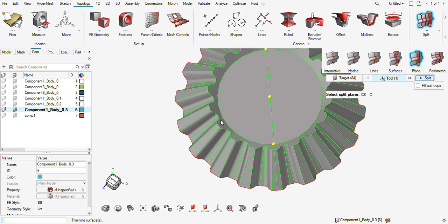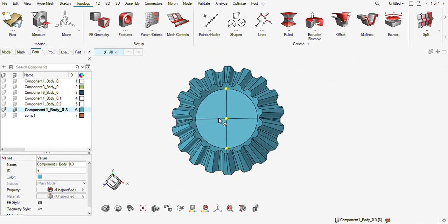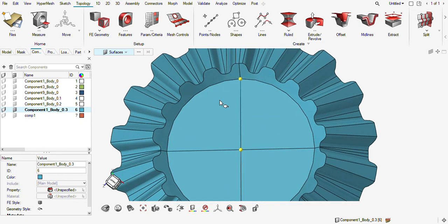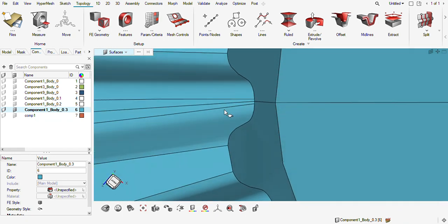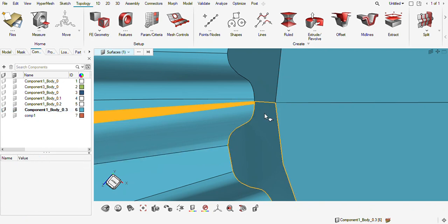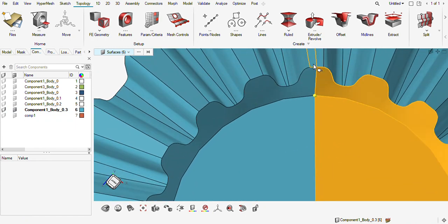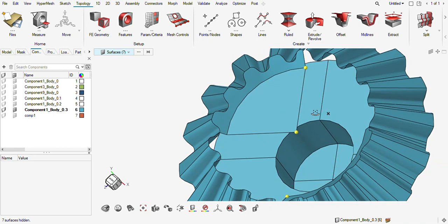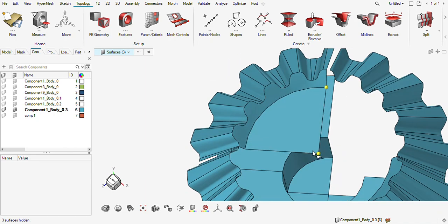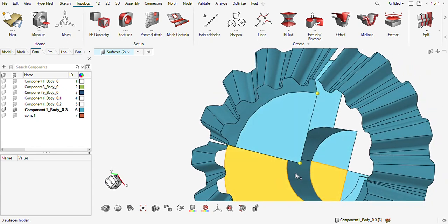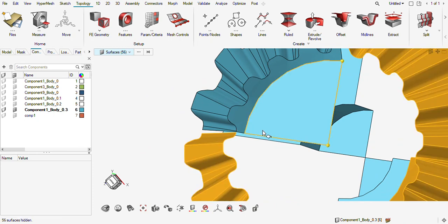So just split this. Okay, once this is done, what I can do here is select one surface and do the rest of the operations in that surface only. So I will simply hide this and this. This I don't need. H. Okay. Now again this surface, this surface, H. Okay. This surface, and this, H. Now again I can just press Control T and hide all other surfaces.